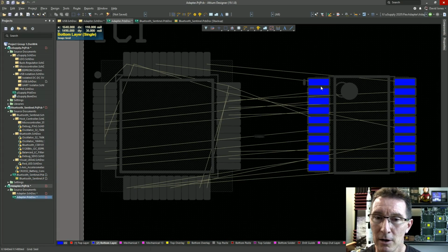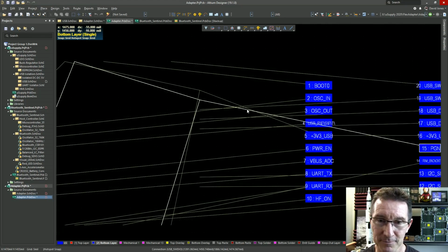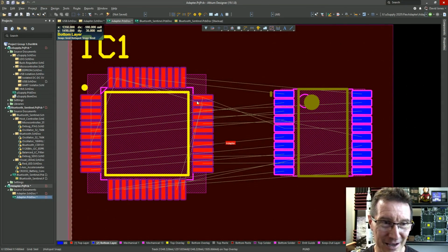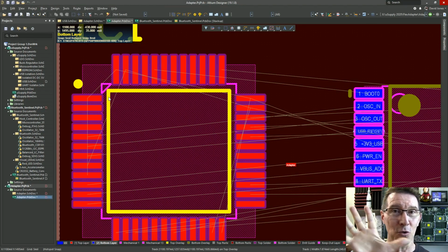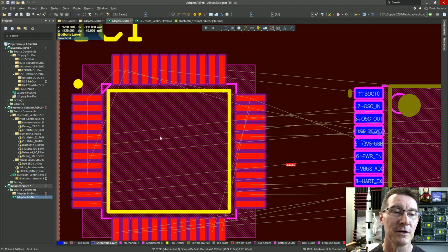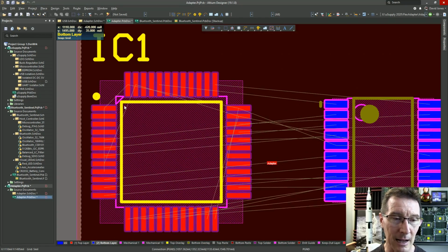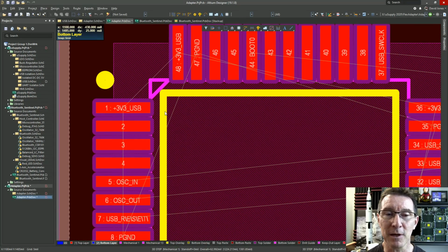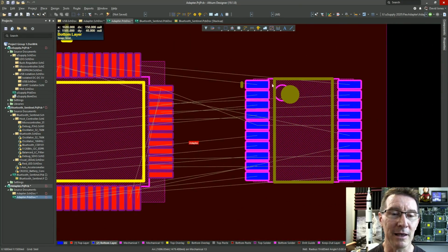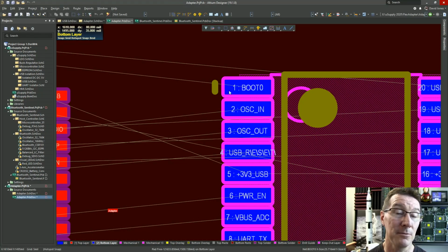So now, here's where you can come a gutser. As I said, you've got to be very careful here. All your PCB designs are always done looking through the board. So this is the top layer. By definition, it's the top layer, so it's the red layer here. This is pin 1 over here. Ordinarily, pin 1's in the correct configuration for the chip. But you'll notice it's blue, it's on the bottom.